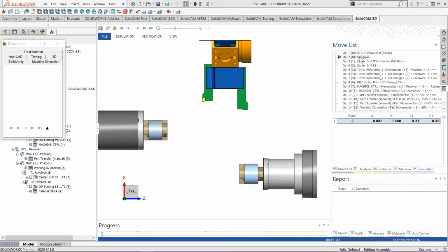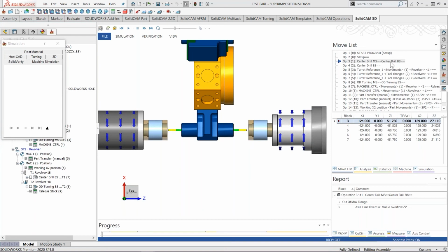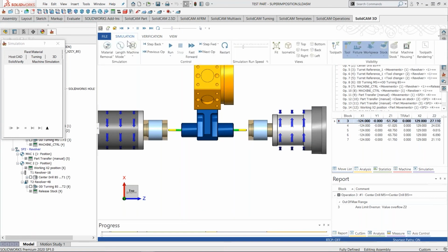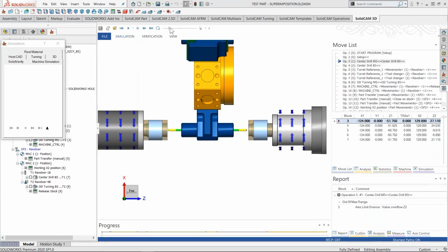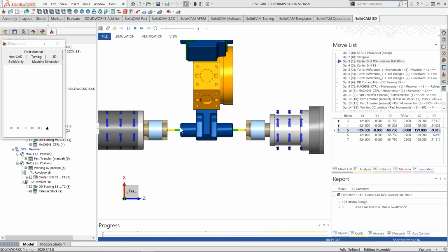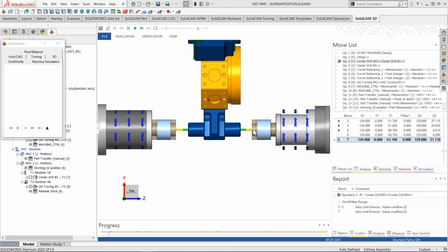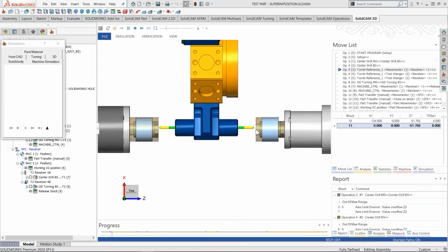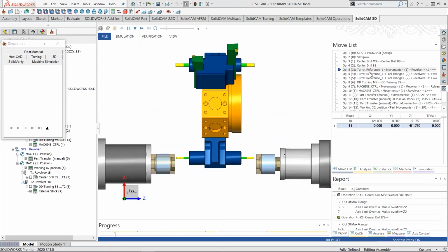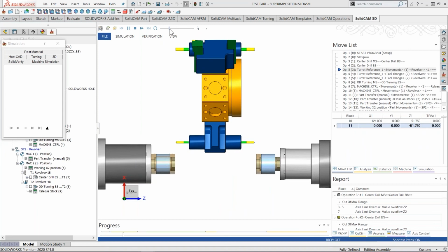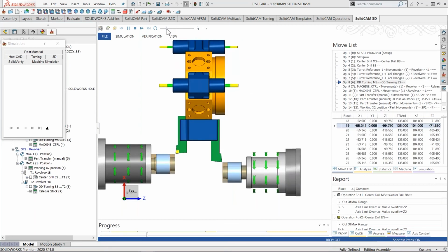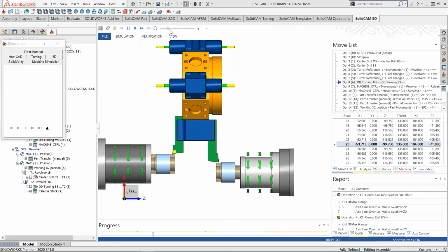Now, if you see, I click on the setup. Now we see both parts because we used the add new workpiece. And now we do a center drilling on both spindles. So I'll just minimize this, go to the length mode. Hopefully you can see everything, guys. So basically the work offset, or dynamic work offset, is loaded on the second spindle as well. We are going up now and basically changing the tool. I want to simulate that, and then the simple turning is performed.